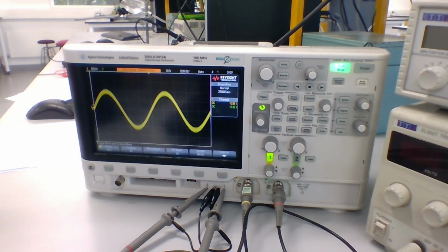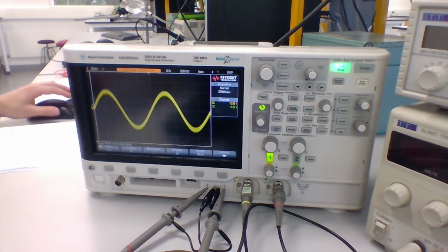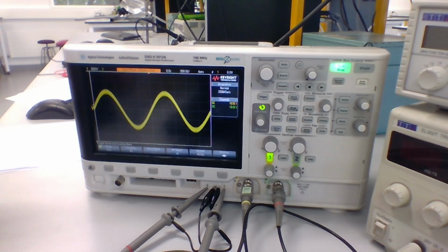And later in the course, we'll talk about active filters, their design, how they work, and how to think about those. You'll also encounter those when we talk about signals in other courses. For now, it suffices to say that what this is doing is saying anything that's happening above a certain frequency, in this case 50 kilohertz, gets cut off or gets reduced. So it tries to reject anything that's happening at a certain high frequency or above.